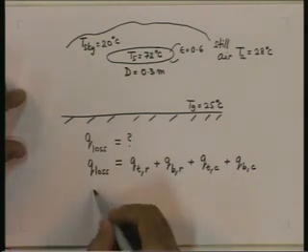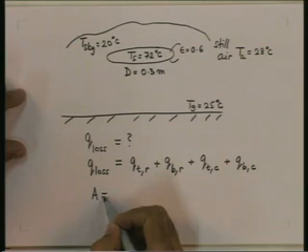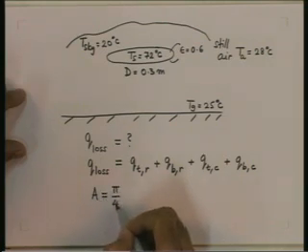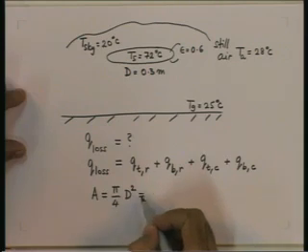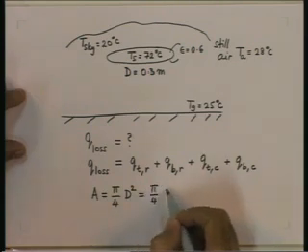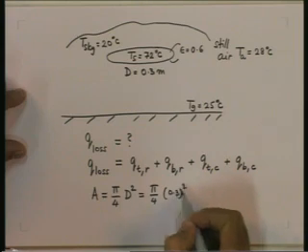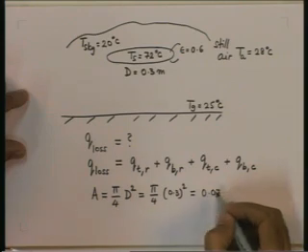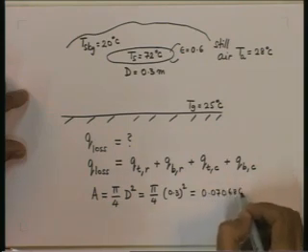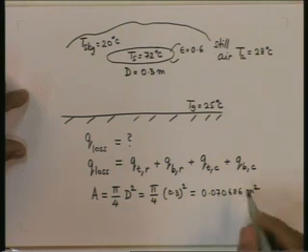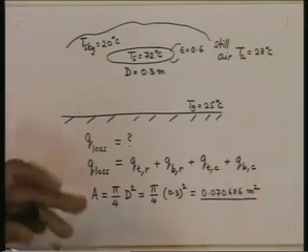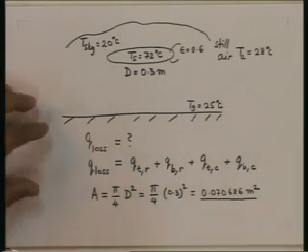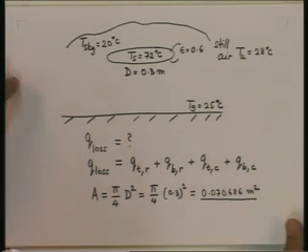Let us first calculate the area of the plate, which we will be needing again and again. This is pi by 4 d squared, which is pi by 4 into 0.3 squared, this turns out to be 0.070686 meters square. We'll use this again and again, so we'll calculate it once and finish it off. Let us compute the components one after another.